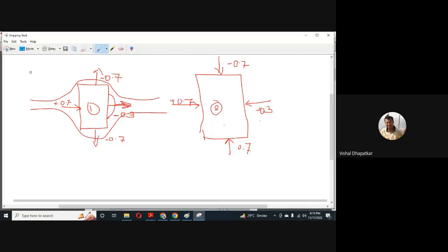Okay, so we have written all the external pressure coefficients, then plus CPI. So we have to add this 0.2. When we are considering plus, it means that it is acting on the wall, right? Earlier we have seen this. When it is minus, it is acting away from the wall. But when it is plus, it is considered as acting on the wall. So here we are considering plus CPI, so 0.2 shall act on the wall. So we have shown the direction of the load. It is acting on the wall.